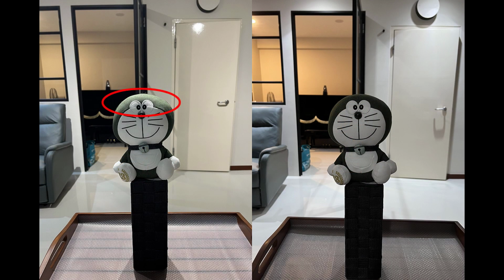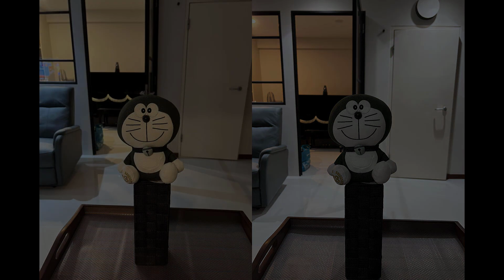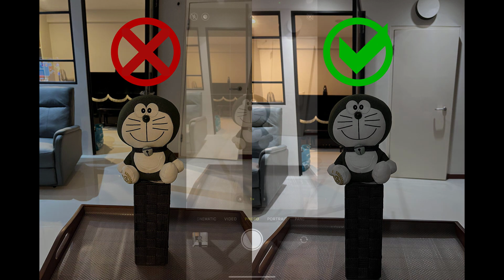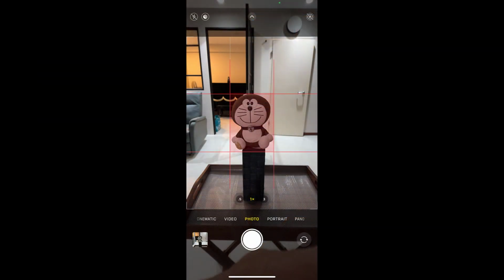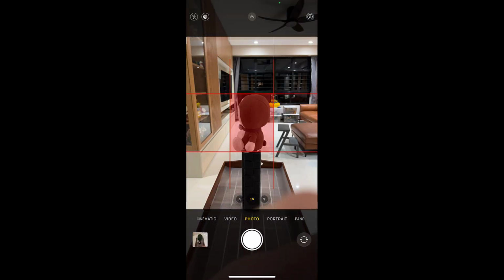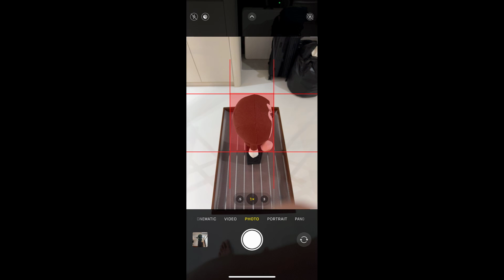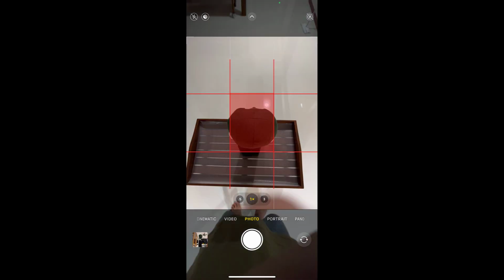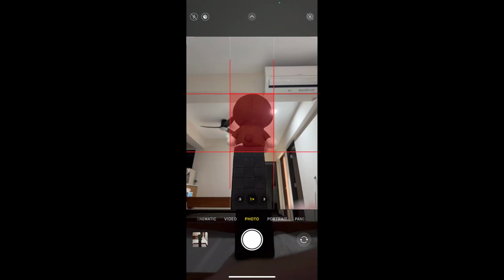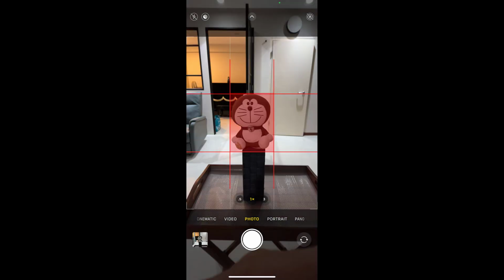Ensure that the lighting is diffused and that no directed light is used. White light should also be used to avoid affecting the base color of the object. Use the camera grid to align the object at the center for every image. This will help maintain high overlap between images, which should be about 70% in all directions to ensure better image alignment and higher model detail.